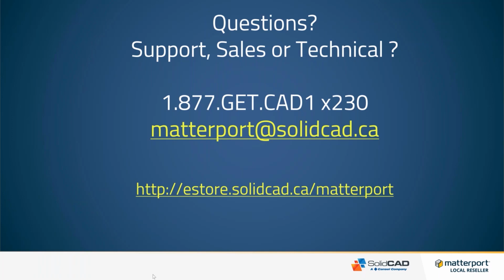So you don't want to be using your Matterport Pro 2 or doing any type of scan during rain or snow or anything like that, or humid conditions. You don't want the buildup of humidity or dust or frost on the lens of your camera, or on the mirror if you're using a laser BLK. The cameras are not intended to be used in those really bad conditions. Try to find a stable, clear day or interior to work with.